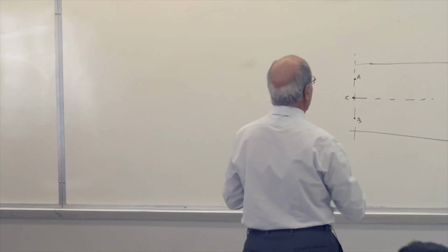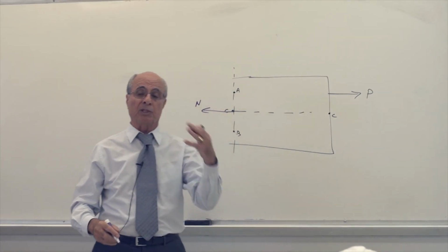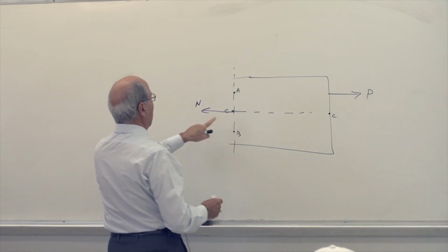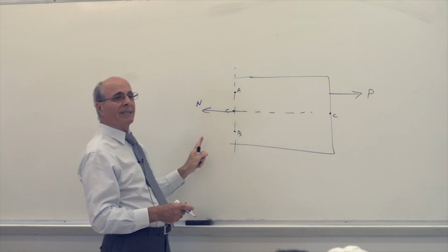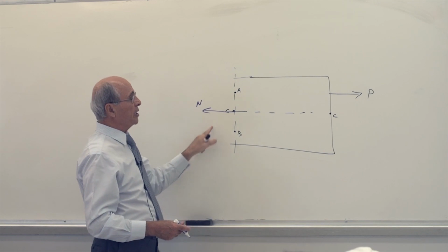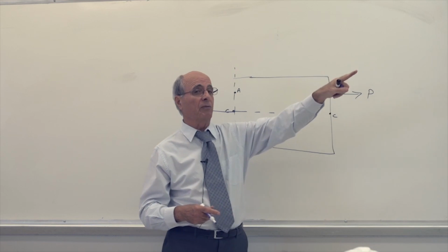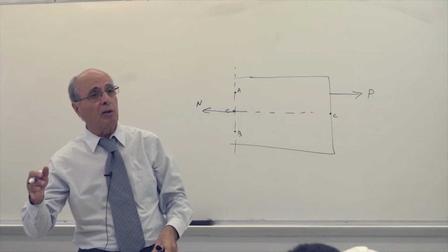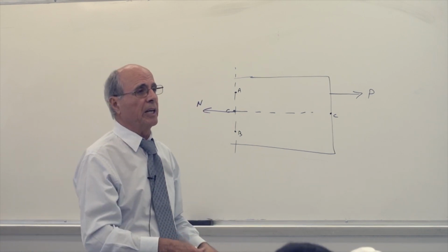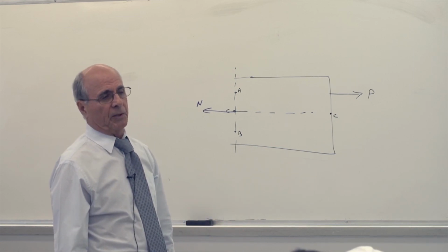Whatever you put here, which we call the normal force, that normal force, which gives you sigma equal to force over area, chapters 1 and 2, that is at the centroid, must be equal and opposite now. Notice this is different from what you were doing there. So this is internal, that is external. Be careful about it. We are going to use the same system here for the shear moment diagram. We have external moment and we have internal moment. We have external action, we have internal action. External is the statics, internal is what strength of materials is all about.